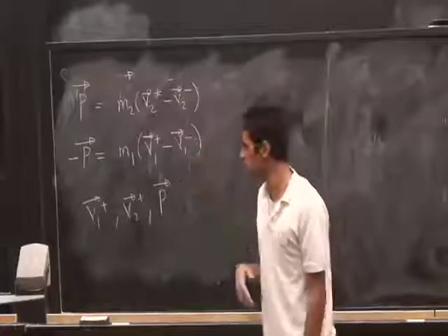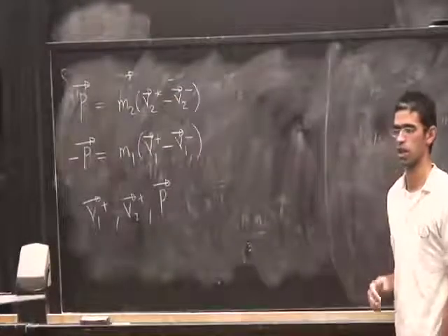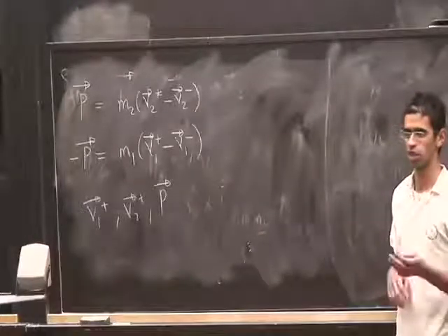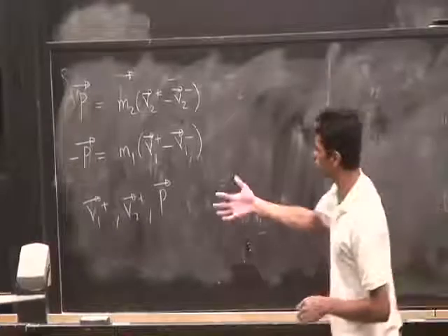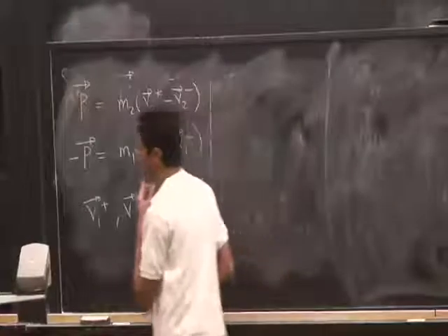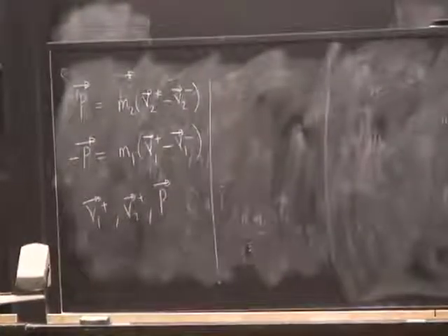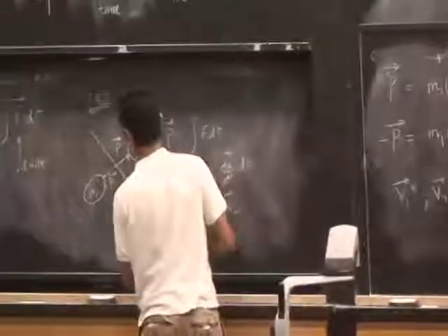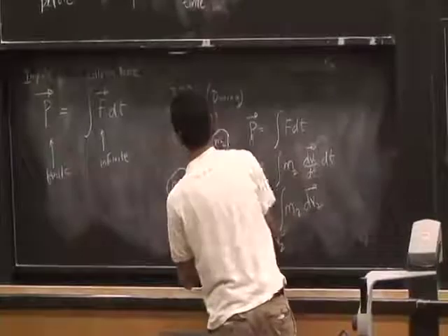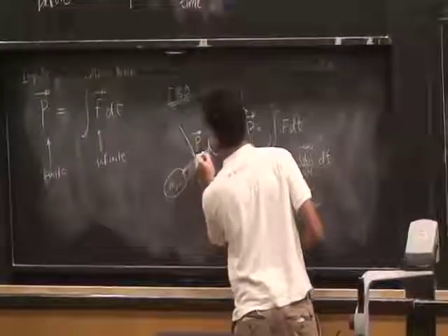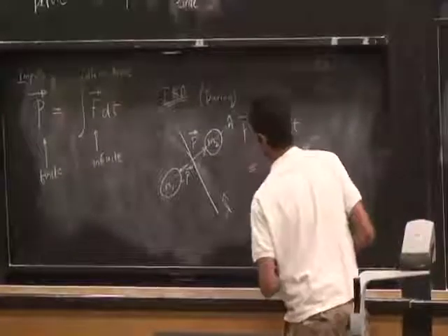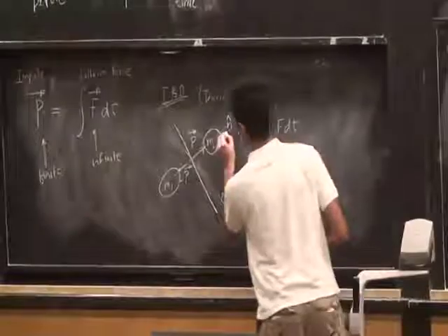And the way we do this is by defining what is called a constitutive law for the colliding bodies. So we will be using what is called coefficient of restitution to generate the last equation. So this is an empirical result. That is, if two masses collide, and let's say that the normal to the surface is in the n direction and tangent is in the lambda direction. So this is perpendicular.